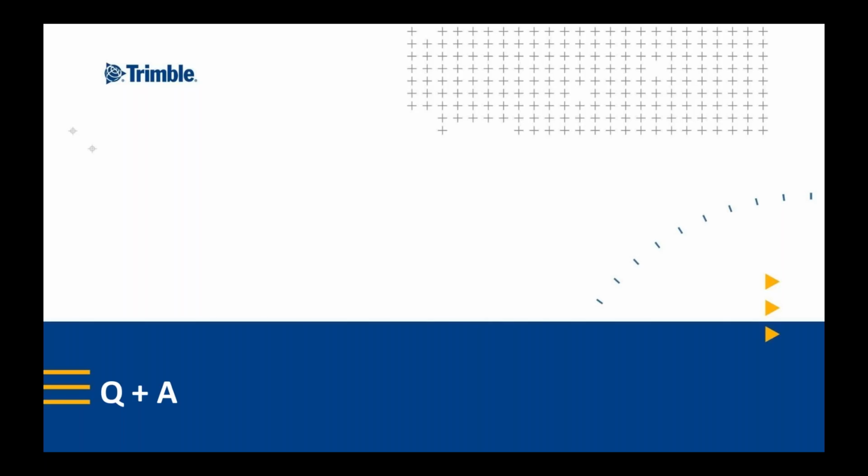Yeah, we've got a couple of really good questions coming in here, and we'll have time to address them. A question came in about other formats. So this workflow specified how TBC and how Trimble Access fit within the Bentley GeoPak roading workflow. The intelligence of the alignment and cross sections, for example, is also supported with the LandXML format if you were working in separate packages and can generate the LandXML as well.